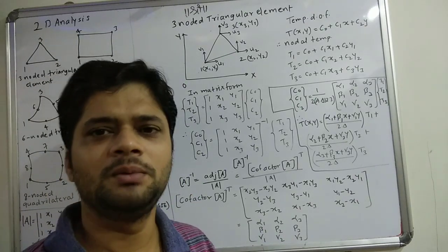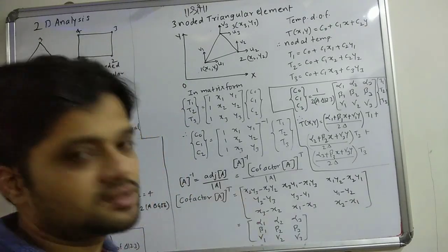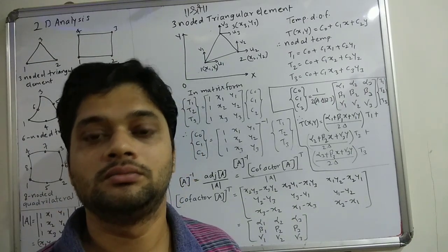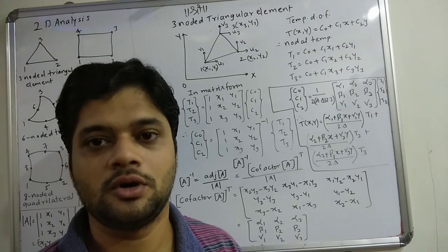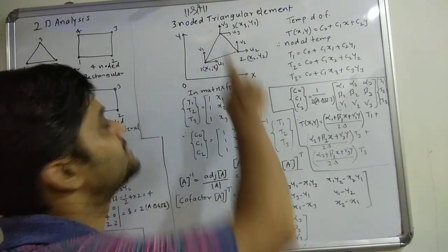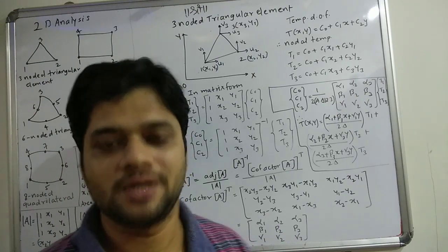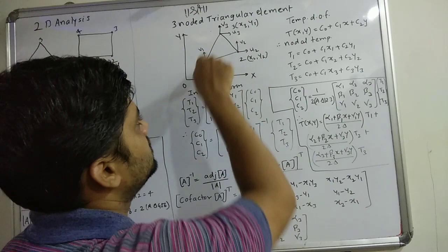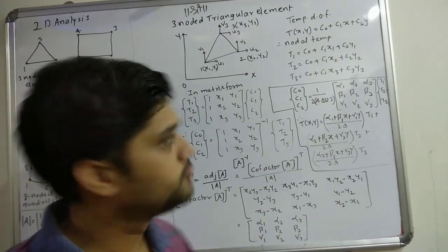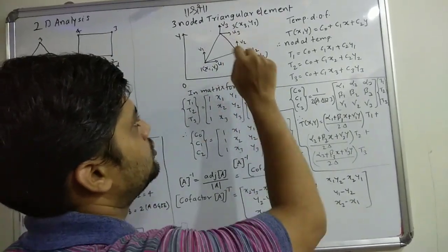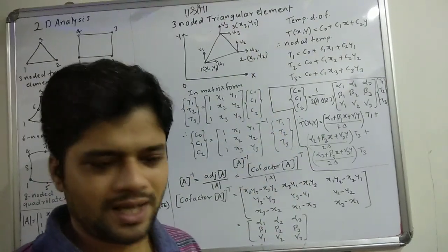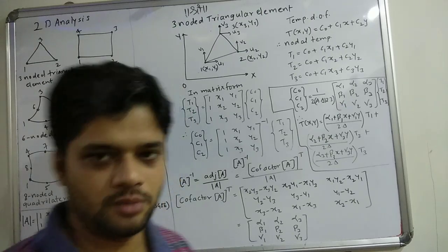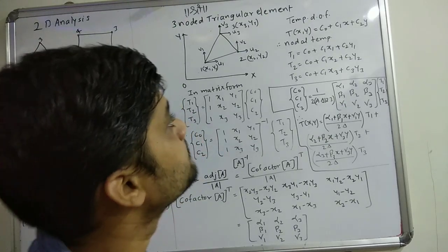The multiplication comes out to be 6, and that is going to be the order of the stiffness matrix for this element, which we are going to find out. Similarly u1 v1 for node 1, then u2 v2 for node 2, u3 v3 for node 3, and from u1 to v3 I have a total of 6 primary variables.